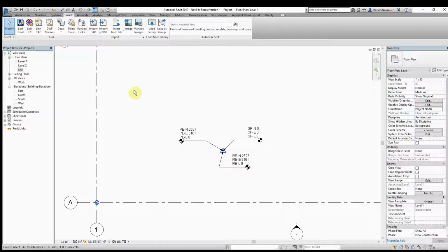So if it's a survey, we can actually do two things now. We can either link it or we can import it. Everyone probably says link, link, link. It's nice. There's just one situation, and it can happen on Friday afternoon. Somebody moved the survey and you have to issue it, and all of a sudden the drawing is gone and you can't issue it anymore. Also, somebody randomly overwrote the survey, and then all of a sudden nothing lines up anymore. The drawing looks really bad.